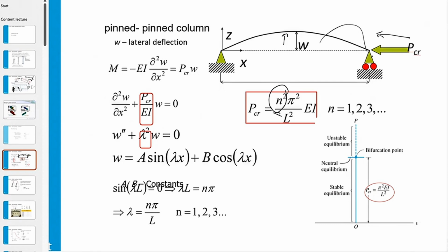The higher buckling shapes, by the way, are important if you have, for example, impact loads. If you squeeze a can of beer or Coca-Cola, you will see that you get a lot of higher order buckling values at the beginning if you slam it. If you slowly squeeze your can, you get one buckling load like this.